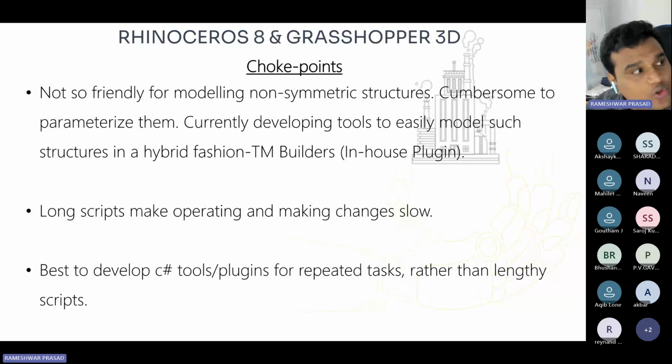Because as structural engineers, we are so used to centerline modeling that we sometimes do not have a good grasp of how the structure actually is in physical space. That's why this way of modeling and working helps the engineer. He doesn't have to spend double the time to model it in, say, SAP2000 or STAAD.Pro or Space Gass, and then again create the same model manually in Tekla. You can combine both of them, so that reduces the design time and design cost, and reduces the load on the Tekla modeler as well, so that he can spend more time checking the fabrication drawings that are generated.